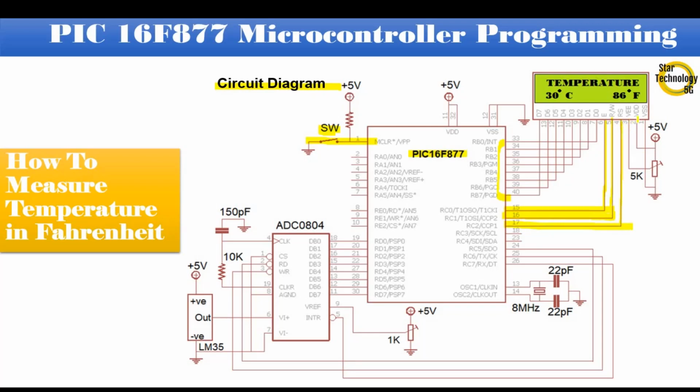Pin VSS connect with ground. Pin VDD connect with positive 5 volt. Contrast pin VEE connect with variable. And the value of the variable is 5 kilo ohm.